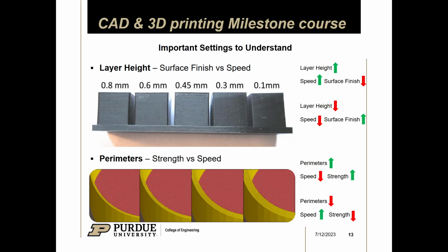But to start, there's layer height. It's probably the first thing that you might go to change. But typically, once you get a profile you like, you don't really change it. But it affects the time probably the most out of all of them. It's basically changing how coarse the layers are, right?